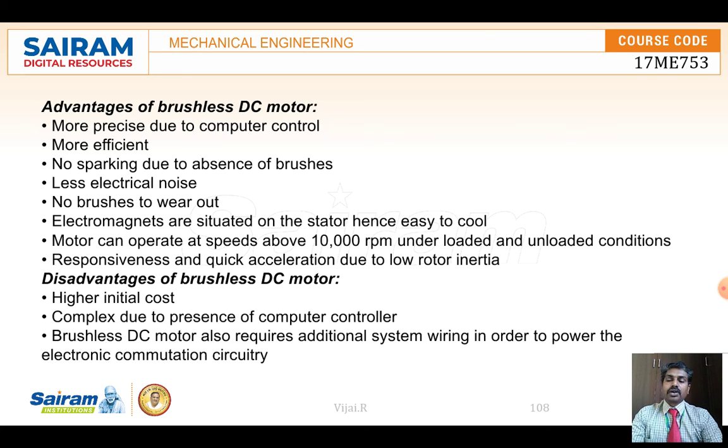Disadvantages: initially the cost, and since there is computer control, it's a complex design, and it requires an additional system in order to power the electromagnetic coils. So these are all the advantages and disadvantages of the brushless DC motor.